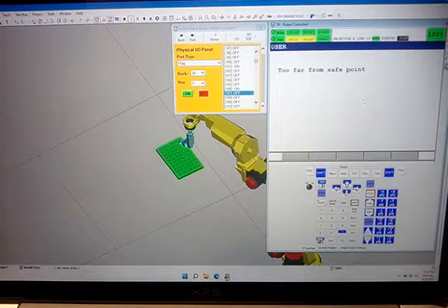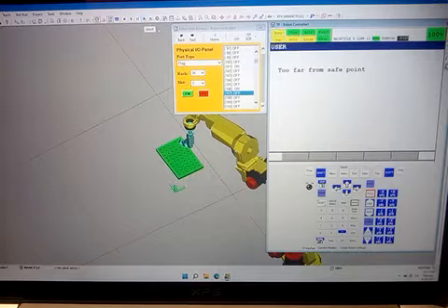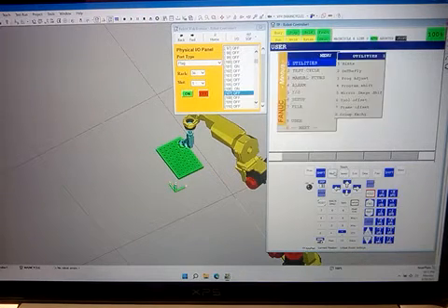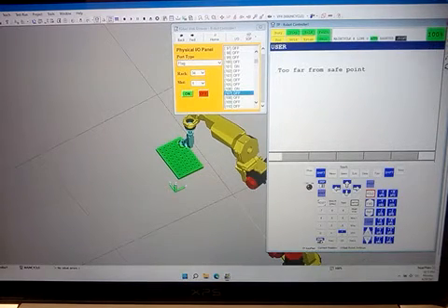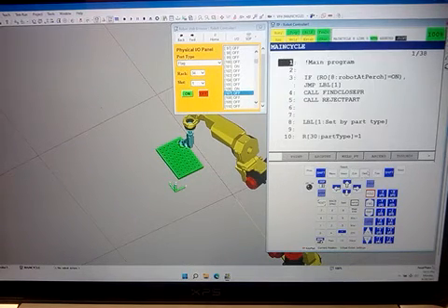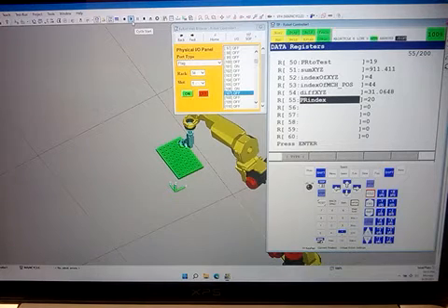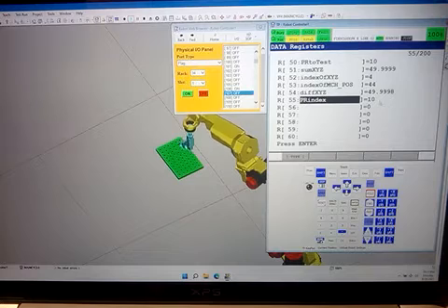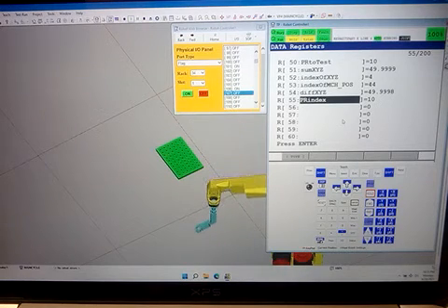But let me abort the program again. So you abort the program. Select new. Function, abort the program, data, select main cycle, data, and let's run this. So it's gonna find point 10 to be the closest.